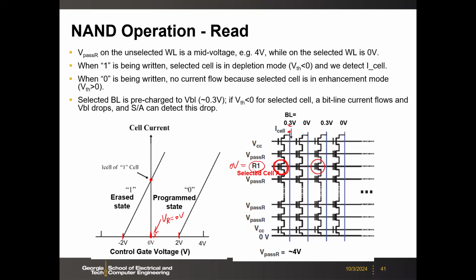But the tricky part is that you have to, again, transfer this bitline voltage to here, through those transistors on the top. By the way, here you cannot ground this ground select. You need to allow it to pass. You need to allow the current to flow. Otherwise, it's floating, and then you don't read out anything.